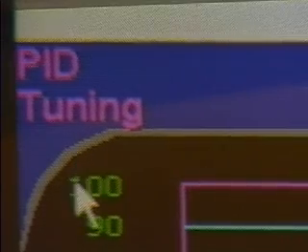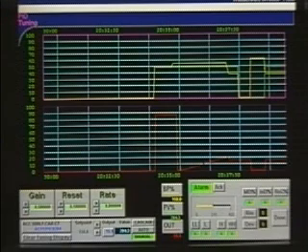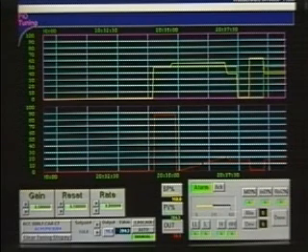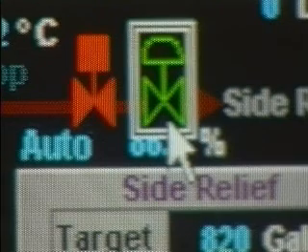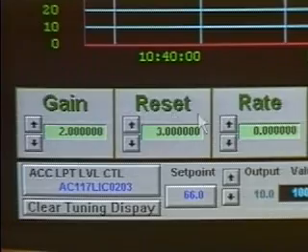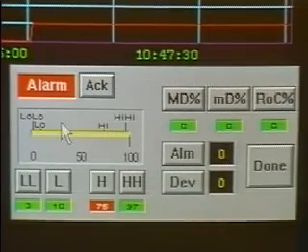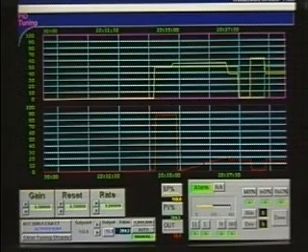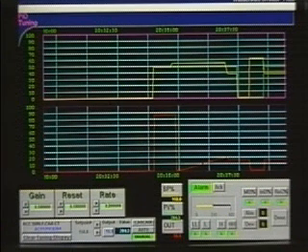When using PLCs, some customers may wonder about the loop tuning displays. Here, loop tuning has been incorporated. By selecting the valve, we call it the loop tuning display here, and then can change the gain, reset rate and alarm limits, modes, and so forth, and have a fast trend for loop tuning, so that the operator never has to go to the PLC program to access these variables.